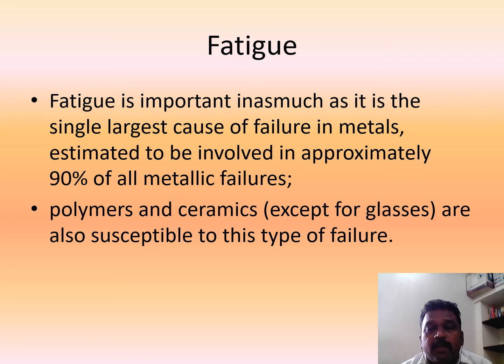It is important because it is the single largest cause of failure in metals, estimated to be involved in approximately 90% of metallic failures. That is, of the failures of machine components or any material structures used, the reason for failure is mostly fatigue. That is, 90% of failures are due to fatigue failure mechanisms. Polymers and ceramics, except for glass, are also susceptible to this type of failure. Even polymers, which have very good tensile strength, will also fail by fatigue.